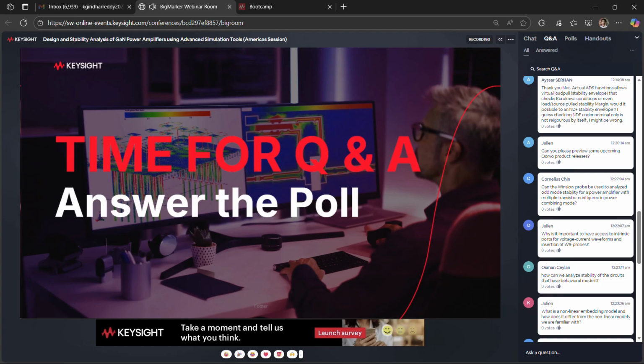Let's just start with the idea of temperature in a global sense, right? And we'll go back to the initial model where we talk about stability as a product of gain and feedback. So if you take a device and you change the gain, well, that's going to change the stability. So temperature, we know for GaN devices and for GaAs devices for that matter, that temperature changes the gain of the device itself. So for GaN devices, if you have a hot temperature, that means that the gain goes down.